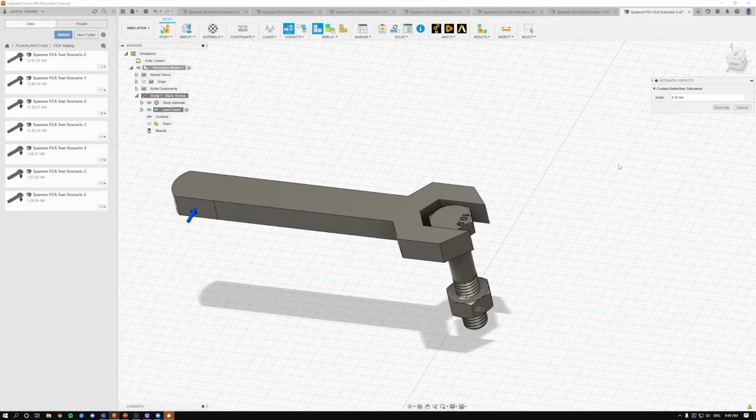Jeremy, I'm just going to interrupt a little bit there, because I had this issue when I started trying to do FEA. I see when you've added a little load there, there's 2 faces on that side of the spanner. And that's very important. Sometimes it can be hard to select where you put the load. If you've got a very curved surface or lots of faces, it will try and apply it to that whole surface. So have you split the face there, Jeremy? Yeah. So you've split the face.